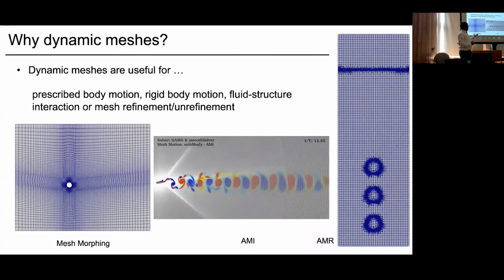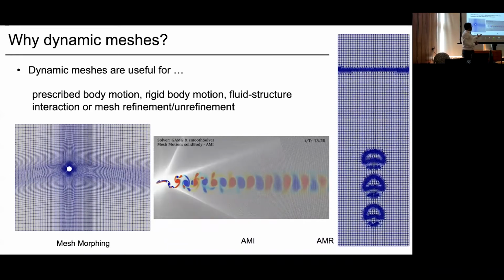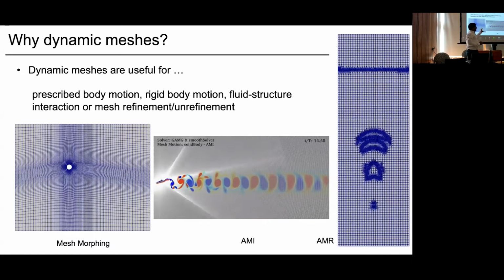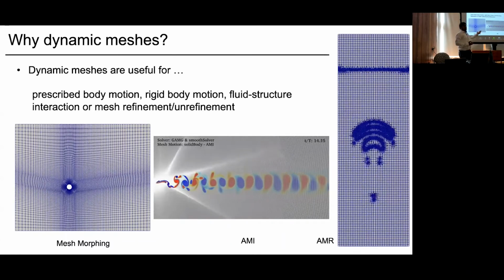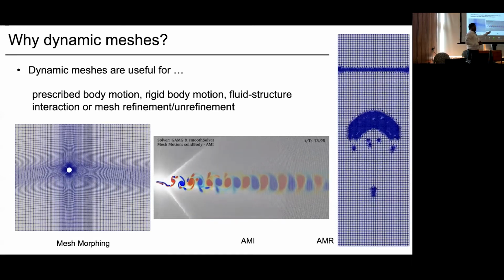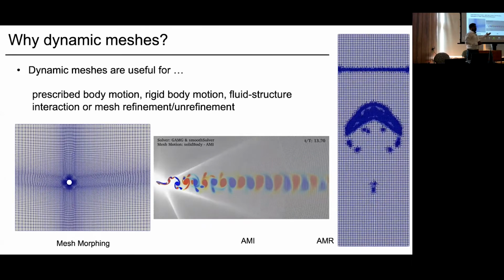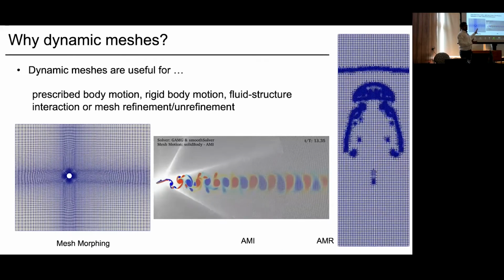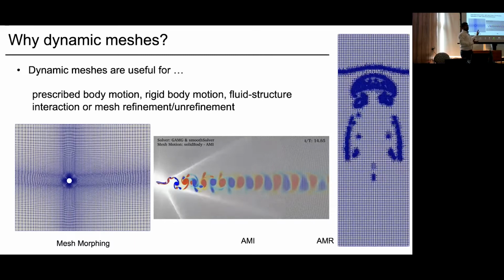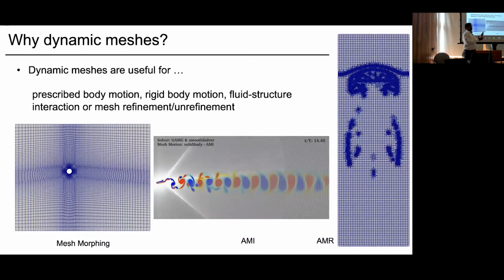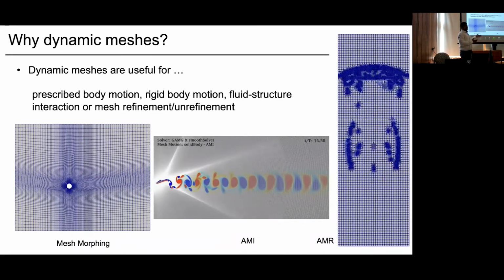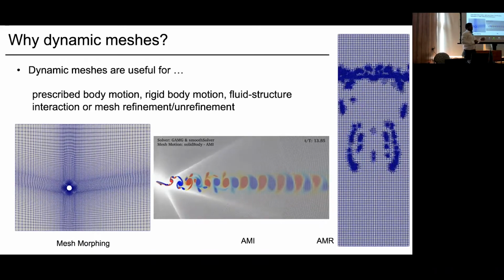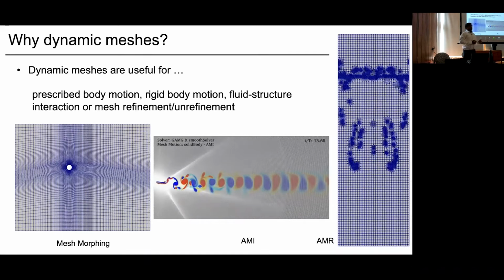The second example, as you can see, is an example of a flapping airfoil, but the inner rotor is only rotating with a prescribed motion, while the outside stator part is not rotating. So basically there are two cell regions in the domain. One region of the cells is sliding over the other region, and the solutions are getting interpolated at the patch, which is an example of a sliding mesh, where the interface is called the arbitrary mesh interface, where the interpolation takes place.